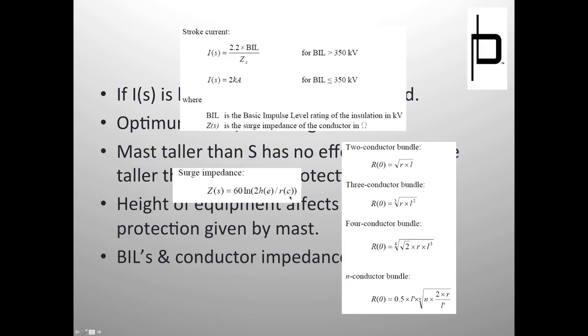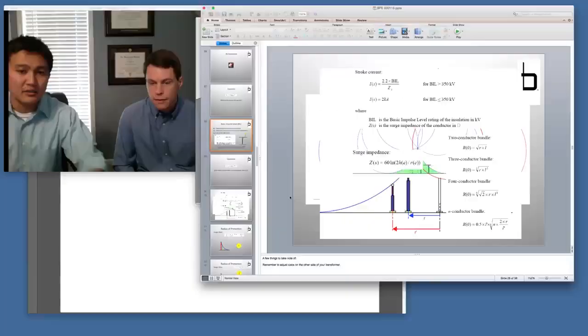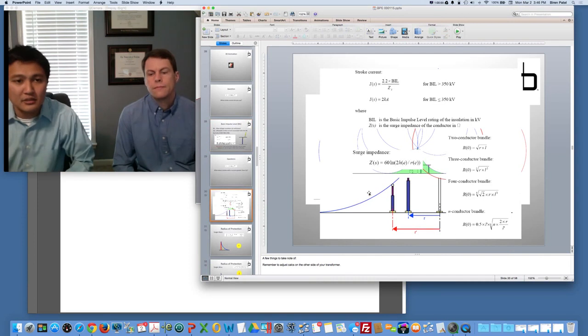But what I like to do is find out which radius of conductor would give me my worst case, would give me my smallest sphere, and use that one, knowing that conductors that give me a slightly larger sphere, I protect against those if I protect against the smaller sphere. So it's just a way to reduce some of those calculations.